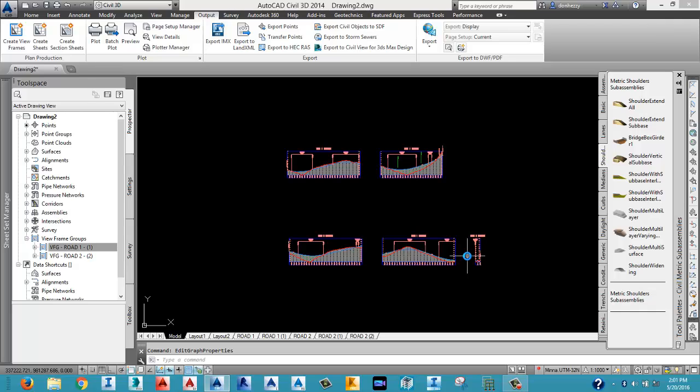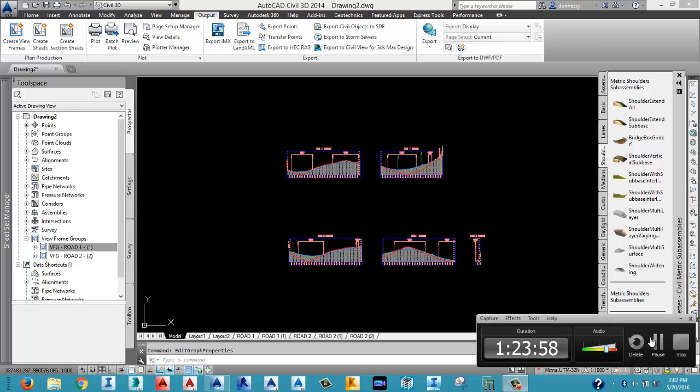Whenever you uncheck split view and your system refuses to process this, you select your profile view again. Go to your profile, right click, edit profile view style, not properties, edit profile view styles. You go to your grid, you uncheck this, click apply. Then you check it back, and click apply. Whenever your system refuses to process it like that, just do that. It updates. So just go through and see what we've done today, because this is very technical. See if you can actually do it over and over, then we'll come back.